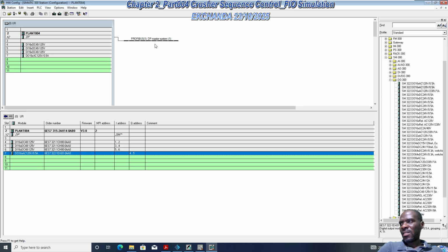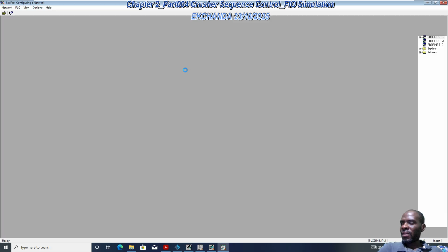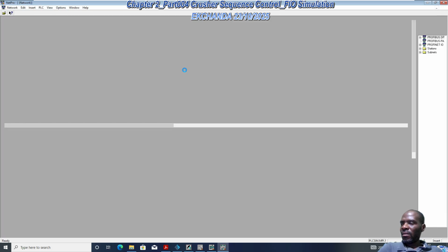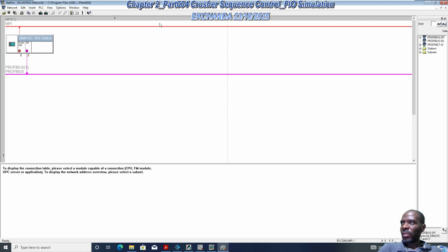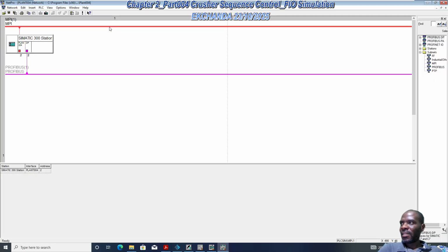Because what I noticed is if you rely solely on this MPI network, or rather subnet, because you usually find them under this subnet category, then without the Profibus, Factory IO in my case wasn't really connecting, or rather it wasn't exchanging data with the Step 7 by way of the PLC system.